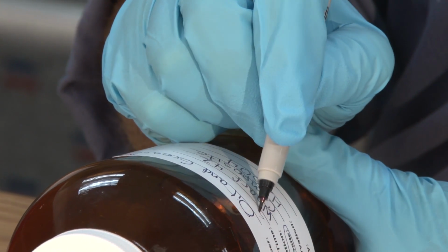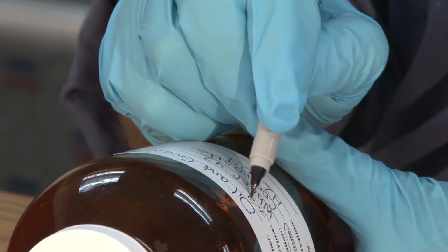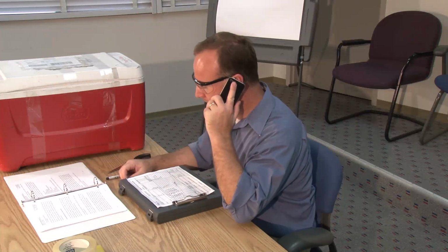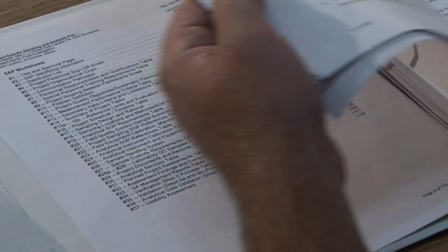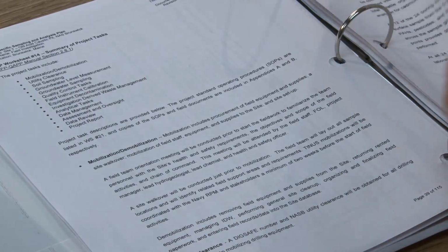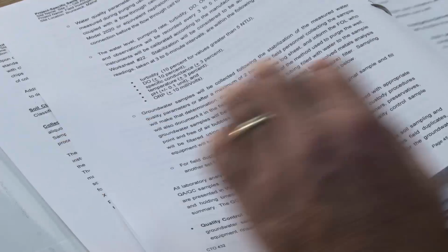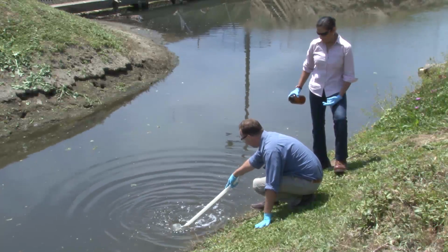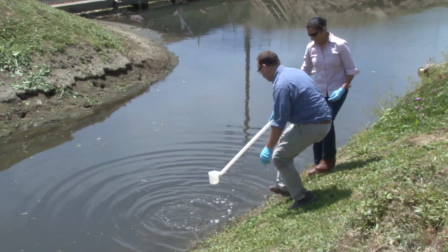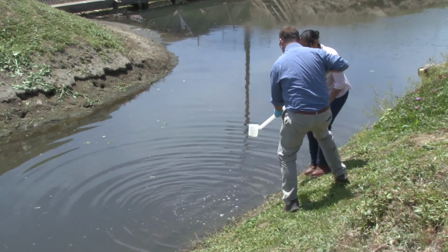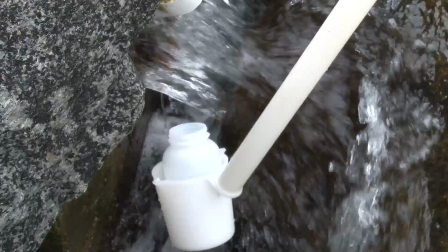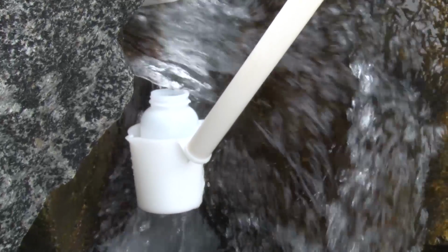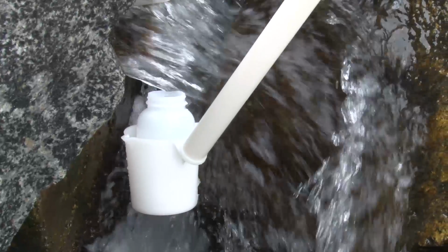Prepare sample containers and labels prior to the sampling event. Make preliminary arrangements for delivery service to have the samples shipped. Review sampling procedures prior to the sampling event. At the sampling point, collect samples, including a grab sample, during the first 30 minutes. Collect samples every 20 minutes for the duration of the storm, up to 3 hours. Special purpose samples may be taken as required in your SAP.